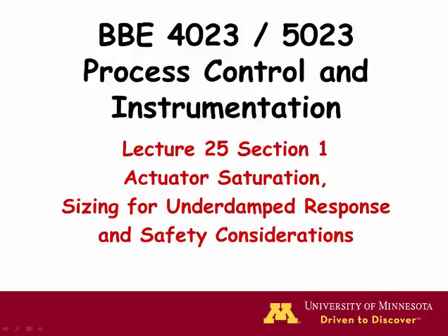The previous videos for Lecture 24 showed how to model time-dependent processes using MATLAB. Many well-designed automated process responses have overshoot, which means that the actuator needs to open more than the steady-state setting. For good, underdamped process response, we will say in Section 26 of the course packet that overshoot should not exceed 25% of the final value after the largest expected step change in any input.